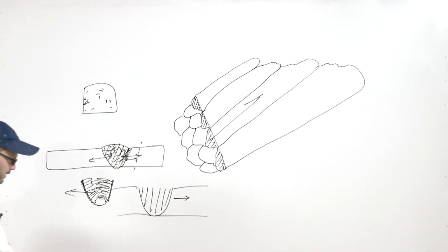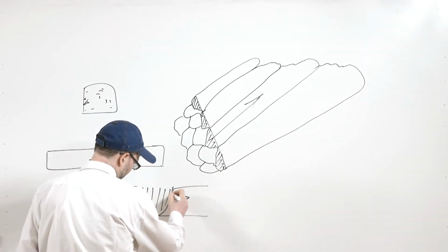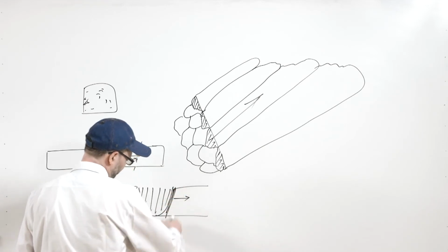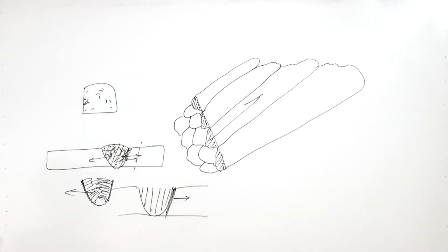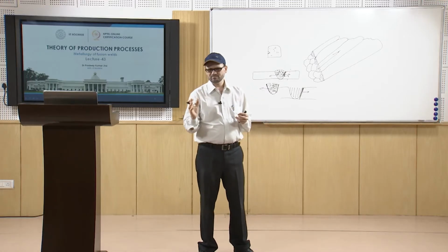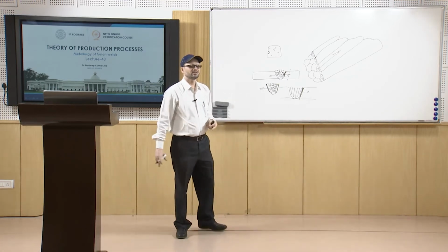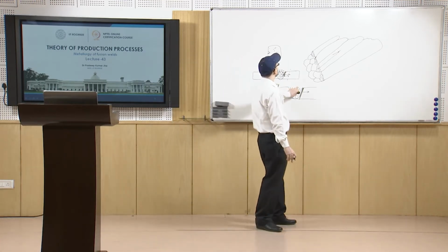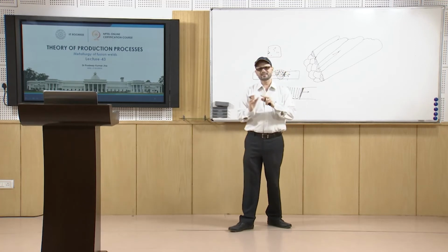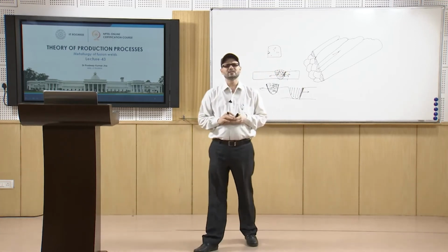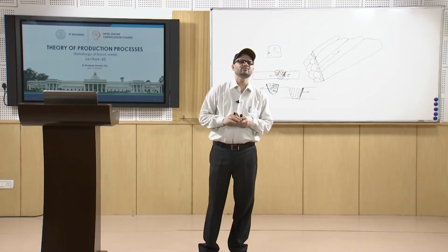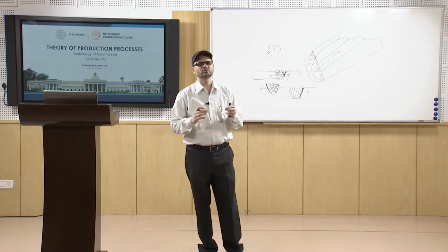In between there is a line, where there is a compositional change. One side you have parent metal with different microstructures, and the other side the uniform weld deposit. So, the demarcation between the two is known as the fusion line or fusion zone.